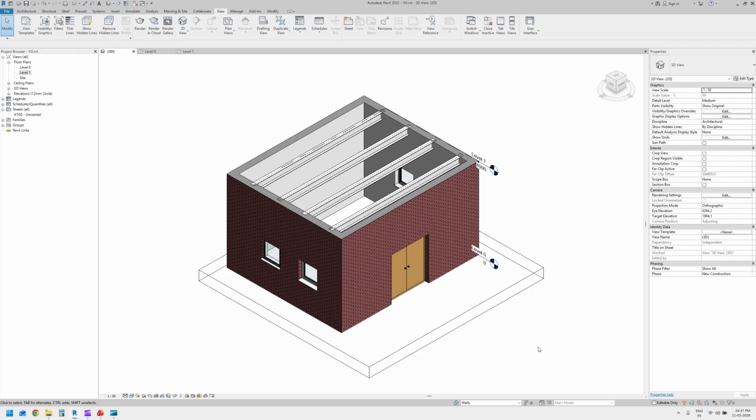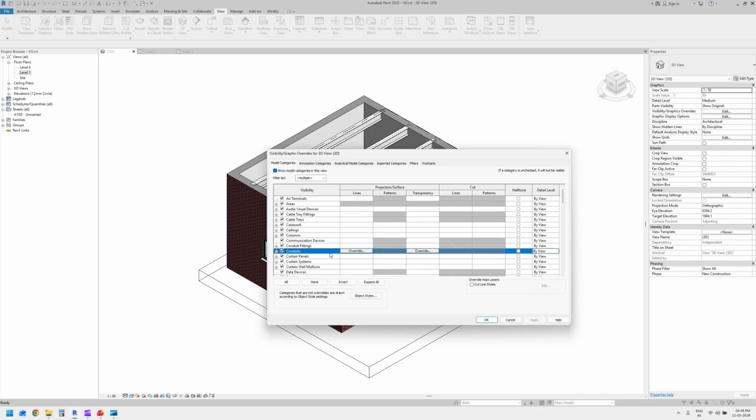In this instance, your floor is just appearing as four lines and there is no solid geometry appearing. This is because sometimes the elements are appearing fully transparent. For this, you should check whether any of the elements' transparency is set to 100%. You can check in visibility and graphics.